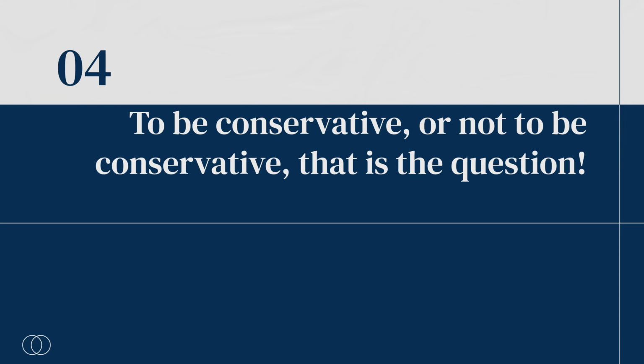As I already mentioned, the history of SPH can really be seen as a history of compromises. The first major compromise was the relaxation of the original Hamiltonian formulation, which was necessary to make the method practical for complex free surface flows. Now we are focusing on a second key question. Does the numerical scheme need to remain strictly conservative, or can we deliberately relax conservation in order to improve stability and accuracy? This question will guide the discussion in the next slides.